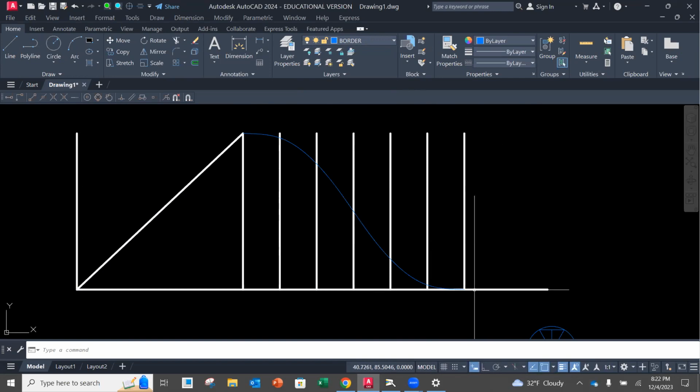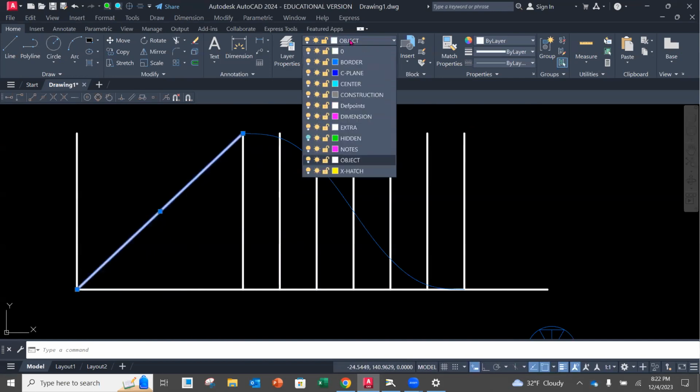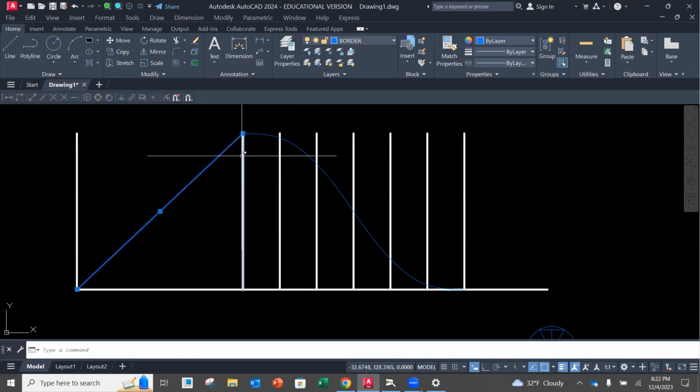Okay. And then this last portion right here is going to be the dwell. Okay. So I rose, I should really change this to my border. That one. I rose, that's my travel. I rose 50 millimeters using constant velocity, and then I fell using cycloidal to the bottom here. And now I dwell out to the end of my 360 degrees.